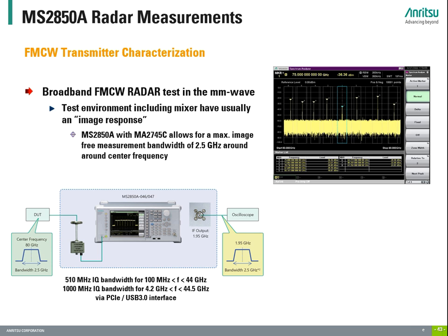Harmonic and fundamental mixer technologies are available in the market, usually from companies like Eravant, VDI, or Olsen Microwave. The disadvantage of harmonic mixers can be seen in the existing image responses and the need for a higher LO power requirement. On the other side, fundamental mixers provide a very flat conversion loss response, a very broadband operating band, but they are quite expensive.